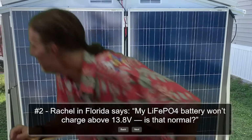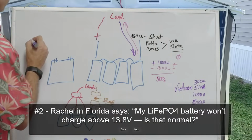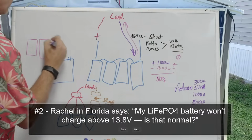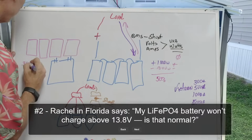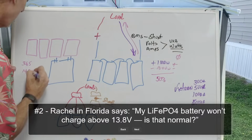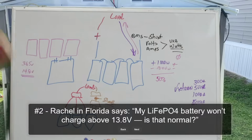And let me explain what I mean by that. So in your case, you have a 12-volt battery, which will have 4 cells, each one of them having a maximum charge of 3.65, bringing you up to 14.8 volts for a full total 100% charged, perfectly balanced battery.